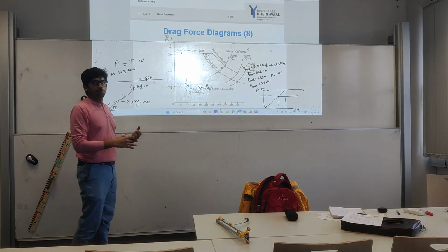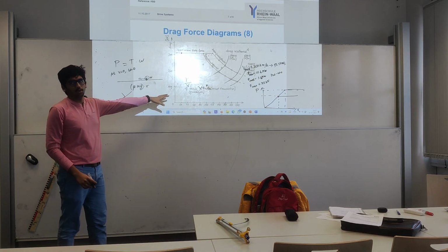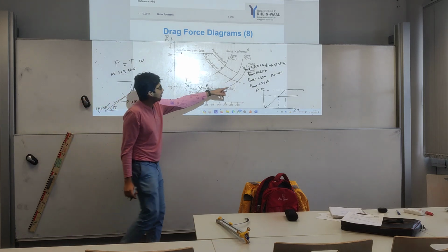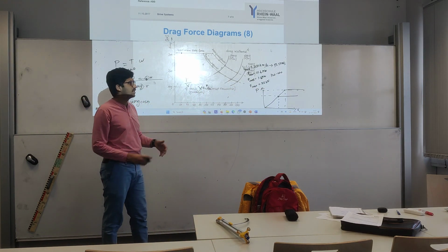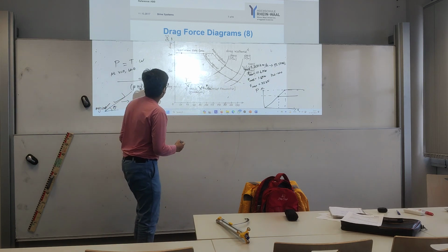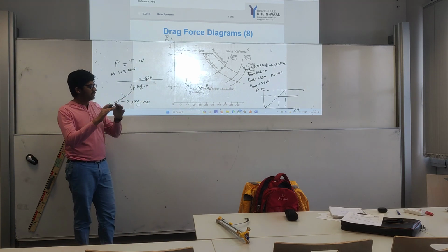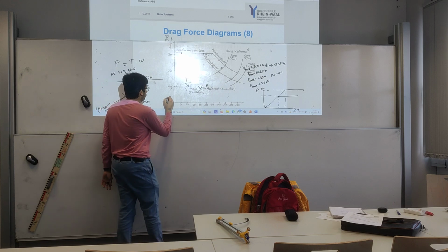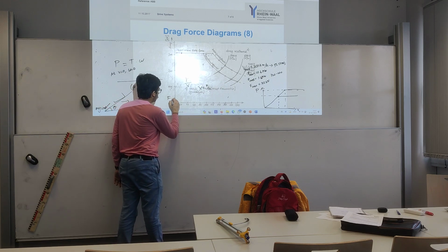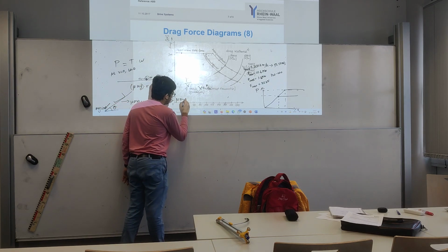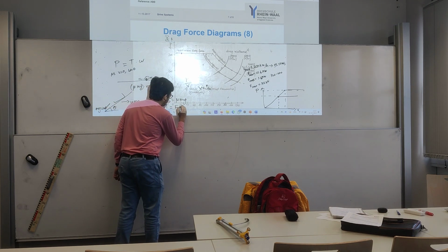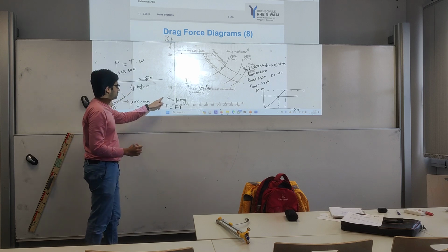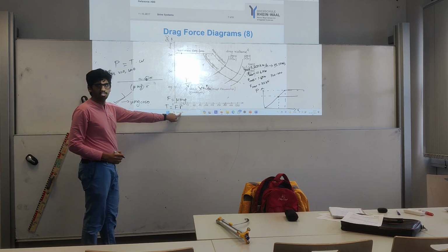So you need to do some preliminary work before you start drawing. The first thing, if here we have the force given to us, but if not, you will find the mg cos theta. So let's say it was given as mg. Friction would be mu mg, and there's no cos theta. Then the torque would be F times R, friction force times R. Radius of the wheel is given to you.